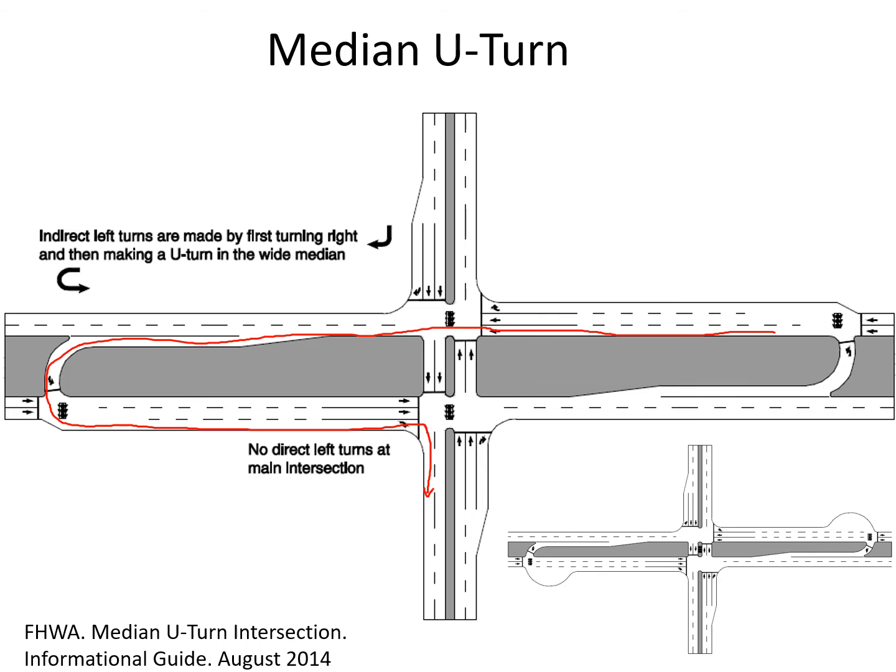The left turn from the side street to the main line ends up looking like a right turn. Come and do the U-turn and then go through. So that's the left turn from the side street to the main line. And you can use bulb outs, shown in this other portion of the image, to allow larger trucks to make that turning movement, with larger turning radii. You can also do it where it's a two-stage merge, so the vehicle can cross the lanes of traffic, then wait here for an appropriate gap, and then continue on with their turn.